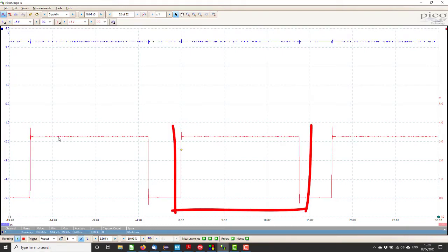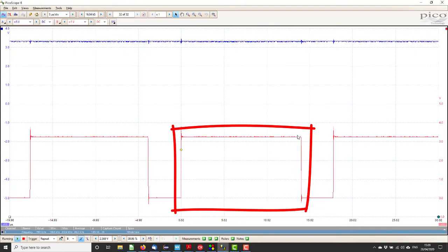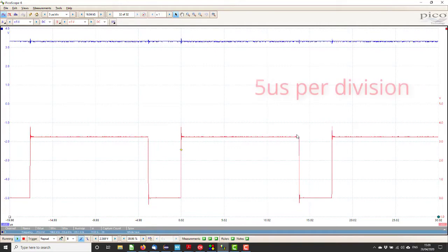And if we look for the second half of the buffer, it's taking 10, well no, 13 or 14 microseconds to put the data out, and it should be putting 32 samples out at 48 kilohertz, so it should be taking whatever that is, 2/3 of a millisecond. So it looks like it's just the DMA is just throwing the data into the I2S transmit register as fast as it can, with no heed to how fast the I2S is outputting it. So there is something seriously wrong.